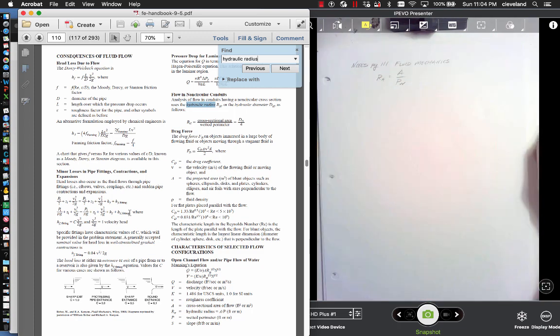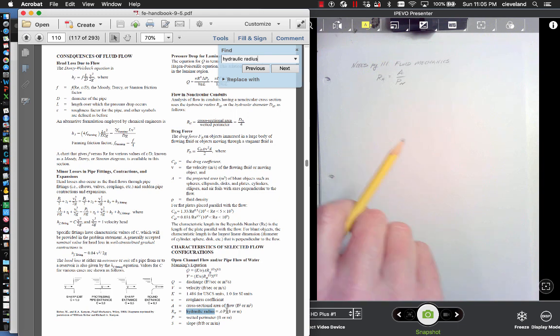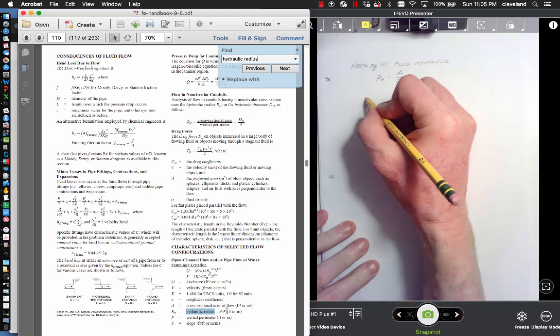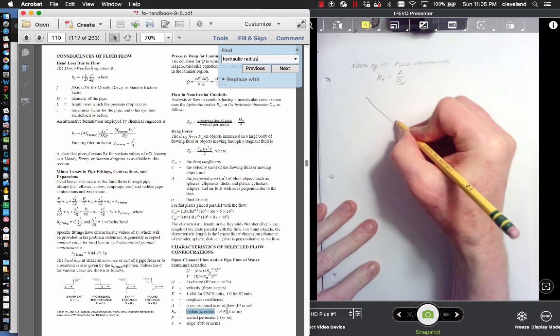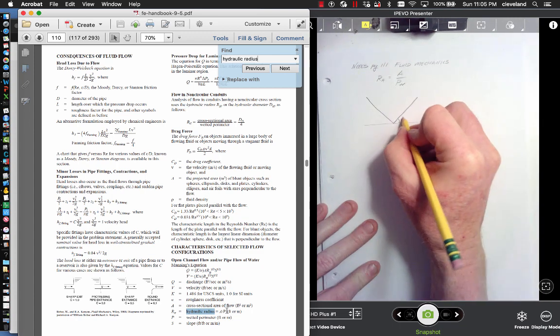Of course, that particular example is for a completely full conduit. And here's a better variant of it, and that's the one we're going to use. They're both saying the same things. Okay, so now we need to figure out the area. And what we're given is a 1-to-1 side slope, which essentially, if that's the case, this is 45 degrees.